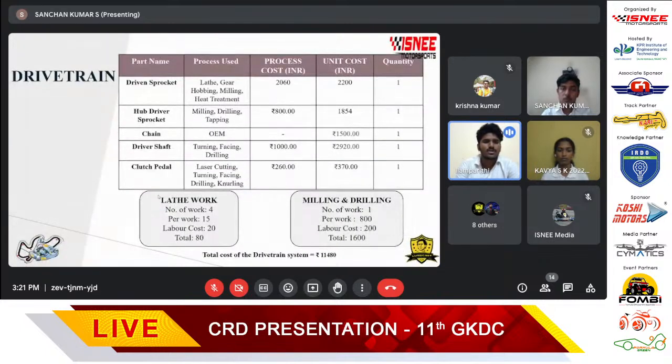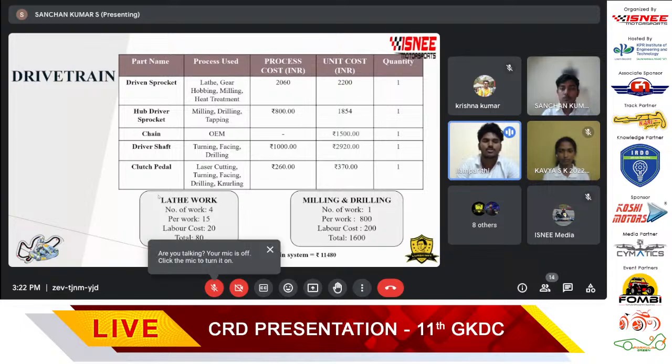When it comes to the driven train, the parts we use are the driver sprocket hub, driven sprocket, chain, driven shaft, and clutch pedal. For the driven sprocket, the process we used is lathe, gear hobbing, and milling. In heat treatment, we used hardening for good performance of the sprocket material. Process cost 2060 rupees, unit cost 220 rupees. The driver sprocket hub, which is used to hold the driven sprocket, is processed by milling, drilling, and tapping. Process cost 800 rupees, unit cost 1850 rupees.